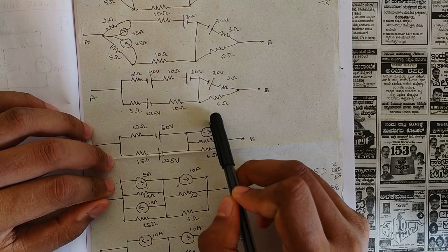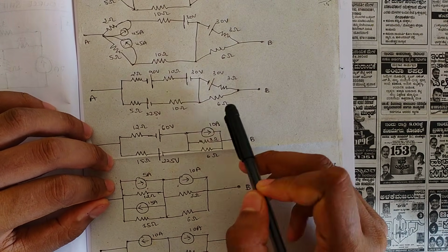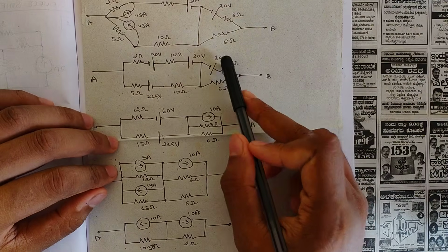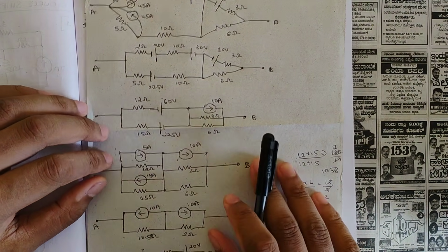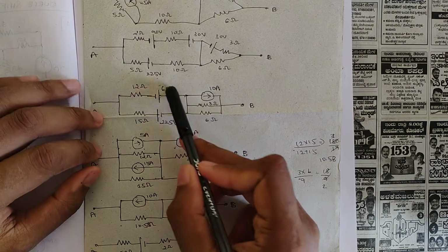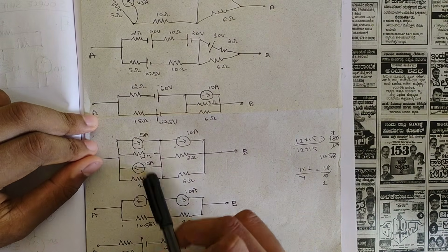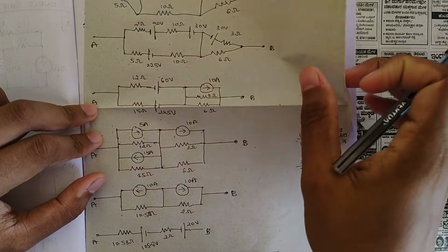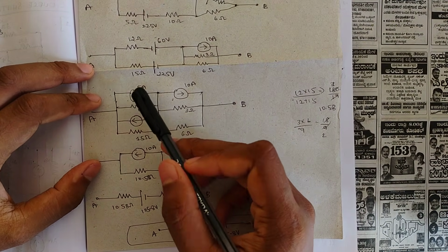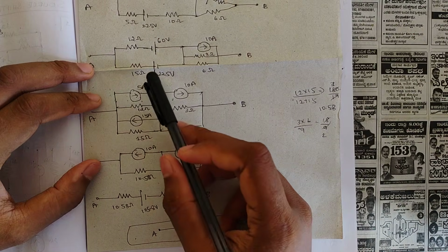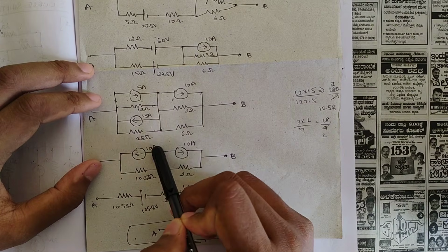Here these two are in a series connection. I've converted it into a parallel connection by adding a current source, that is I equal to V by R, 30 by 3 is 10 ampere with the current direction. 3 ohm I've kept as it is, and 6 ohm. Then we can see that these two are in parallel. Before that, these two are in series, so convert them into parallel with the current source like this. After that, these two current sources you can subtract, because they have different polarities. The greater polarity is this one, so I've kept this here. 15 minus 5 is 10 ampere.